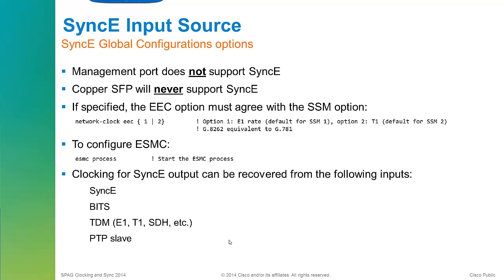There are basically not enough pins in the actual SFP to be able to do it. Some people have tried, and there are some proprietary solutions where they can send it in one direction, but there are all sorts of issues with them. If you have questions, you can probably find the answer on the web. There are very good reasons why it doesn't work properly, and it's all to do with the hardware support and the original Ethernet standards.